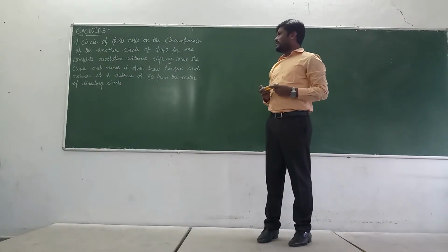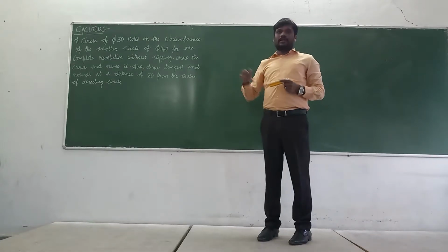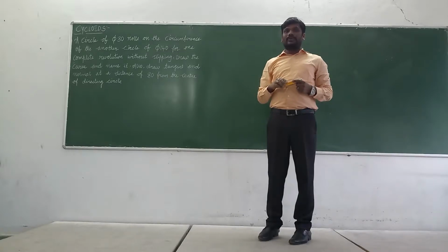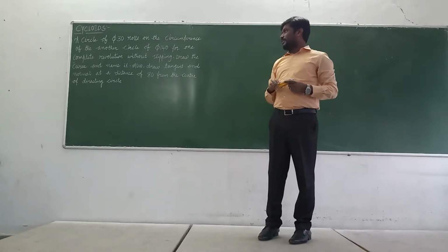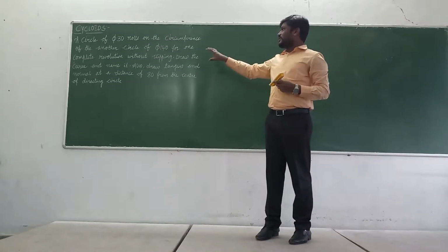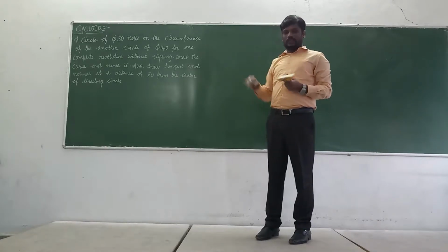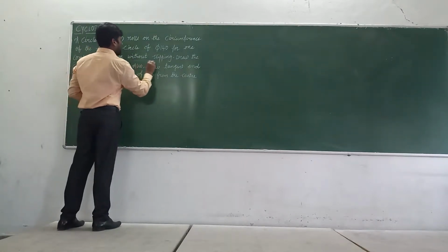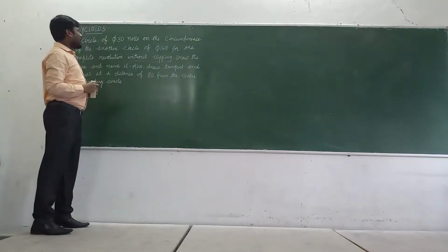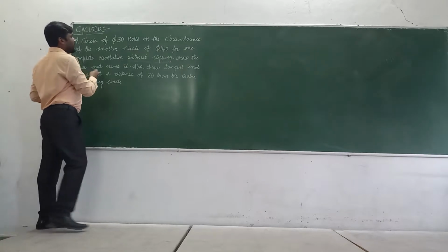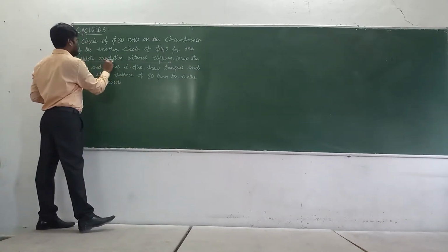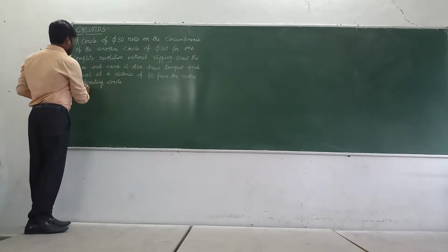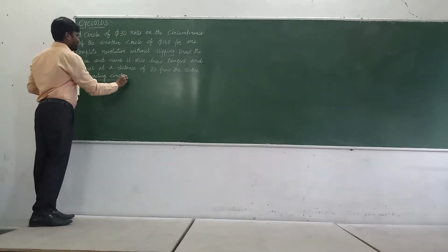I told you in the last class to find out what type of curve this question relates to, whether it is a cycloidal curve, an involute or a conic section. I told you to find some words or hints from the question. When you look at the words without slipping, it belongs to cycloids. I even told you one complete revolution, or terminology like directing circle.